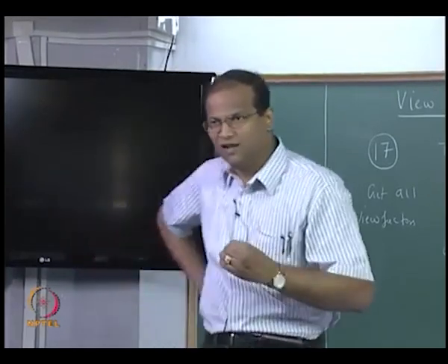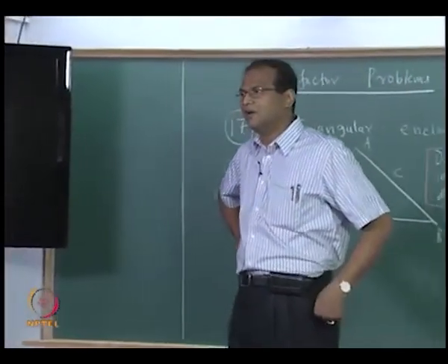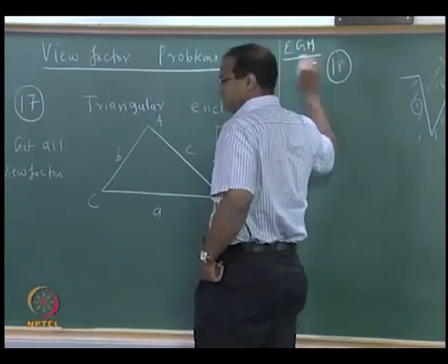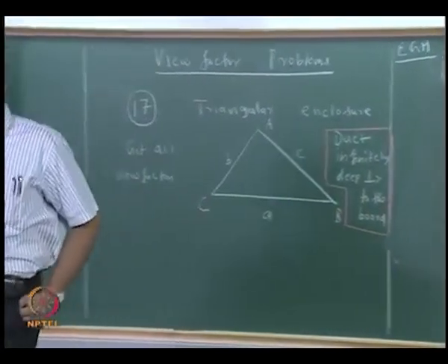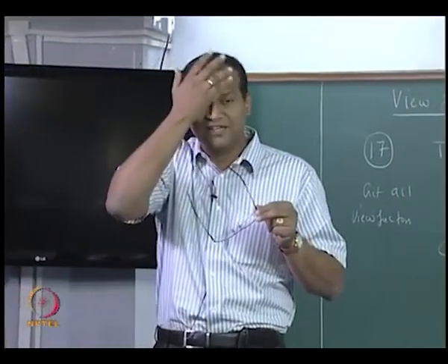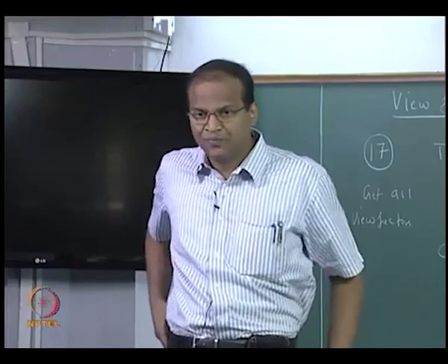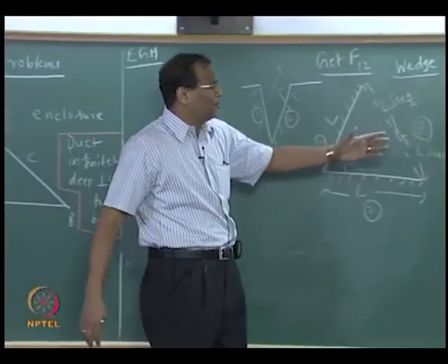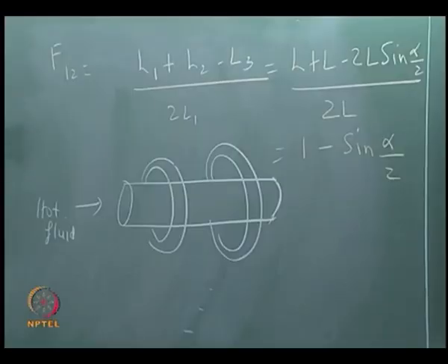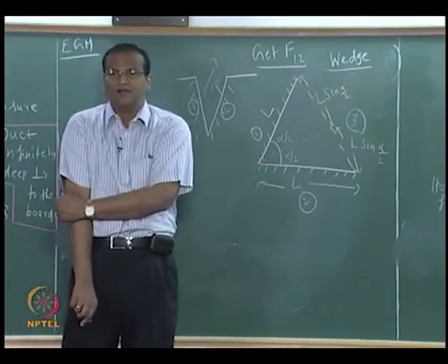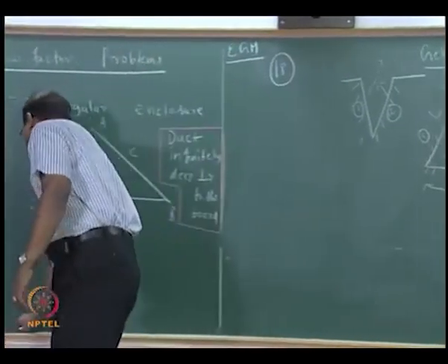What I have just explained to you is a 2-minute course on a very important topic called EGM, entropy generation minimization. That is a well established field by itself. Professor Bejan has written a book on entropy generation minimization. So there are umpteen ways of optimizing. Your optimization in heat transfer does not always mean that you want to maximize the heat transfer, right. Sometimes you also want to minimize the pumping power, or you want to have a trade off. So we will stop it at that stage.